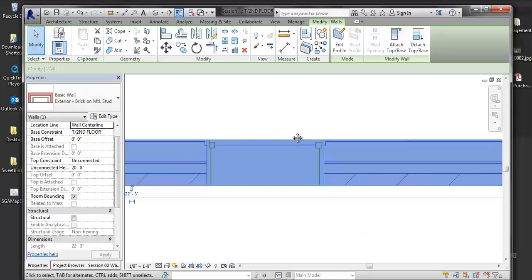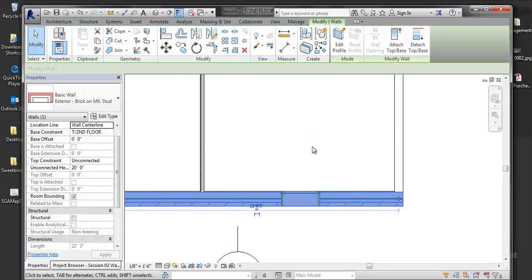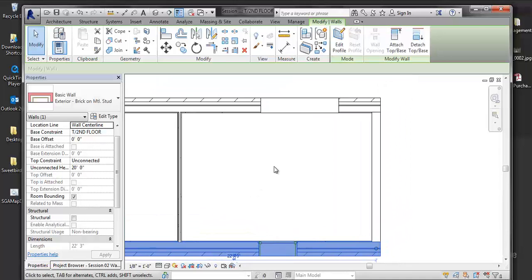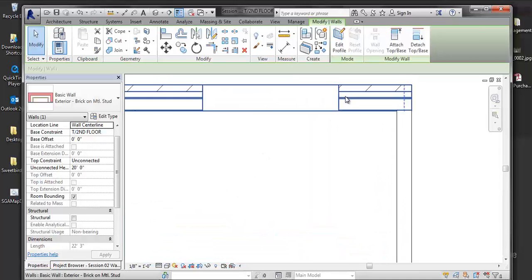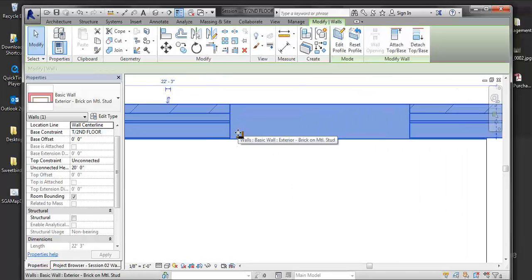And again, like Aaron said, this is kind of fussing about some things. Sometimes it's too early to be fussing about these. Sometimes it's not too early to be fussing about them. Same thing happening with this object, right? Even though I've made a cut in the wall, because it's handled as an exterior function and not an insert, that opening is going to be treated with the end wrapping, not the insert wrapping. Okay.